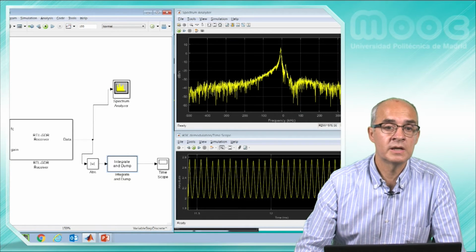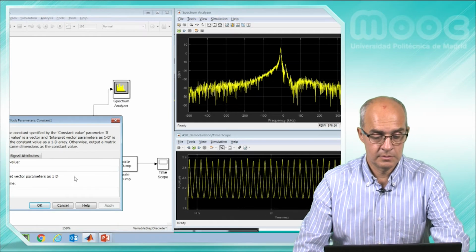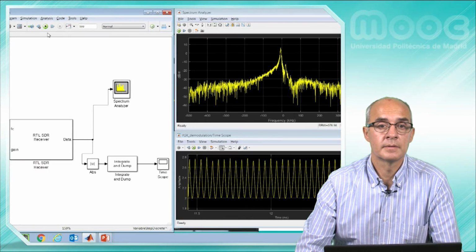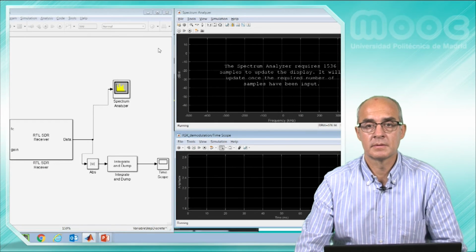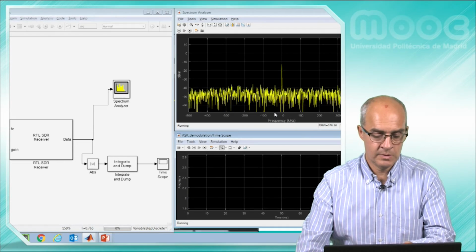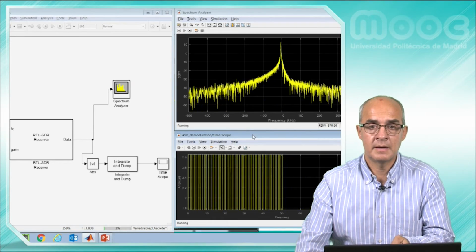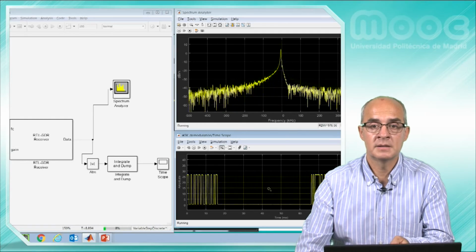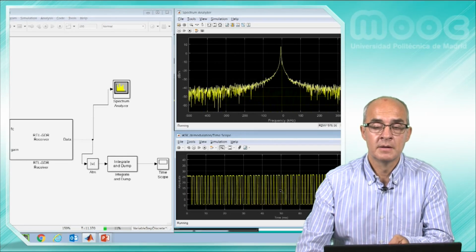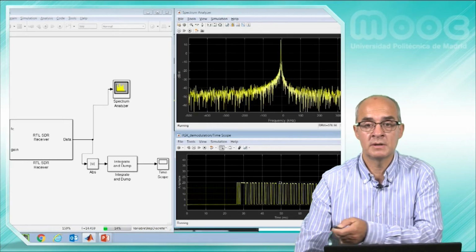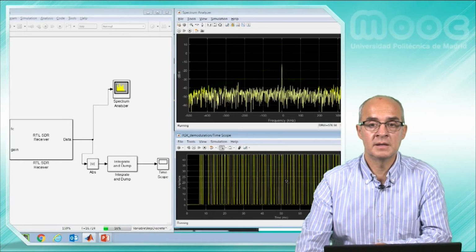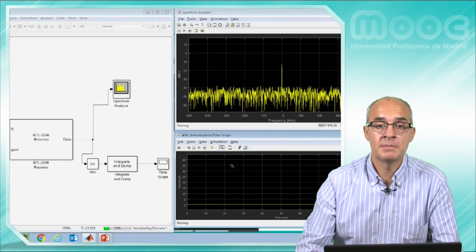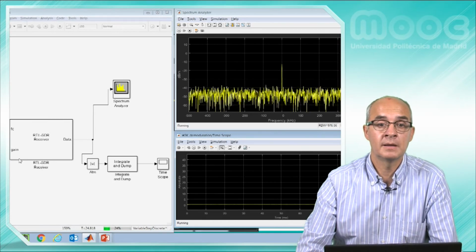And now we are going to change the gain to different values, for example 10. Now it's working, and you can still see that the data has a very good signal to noise ratio. It's very clear. But the problem of ASK modulation is that if I move the transmitter, there is a strong change in the signal amplitude over time. So it's important to use automatic gain control.